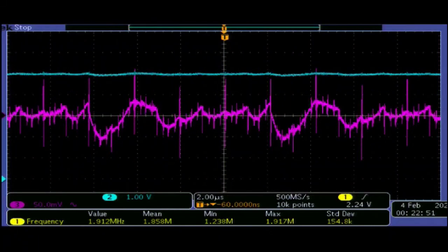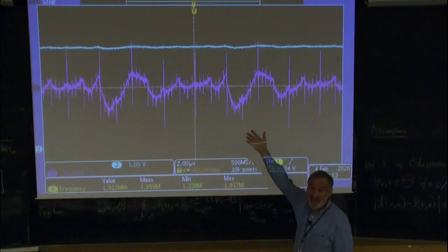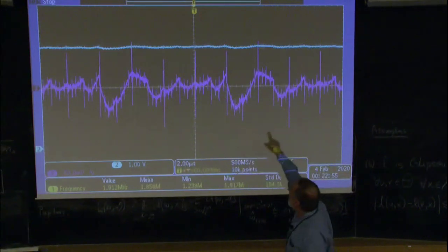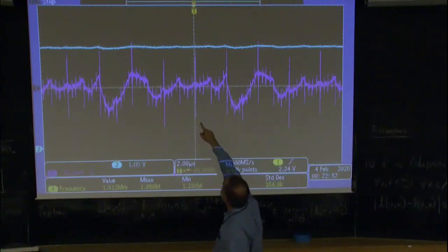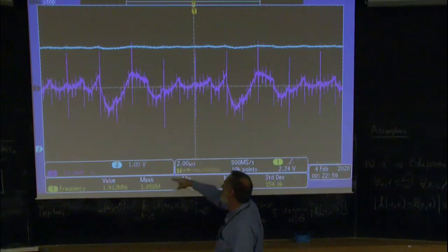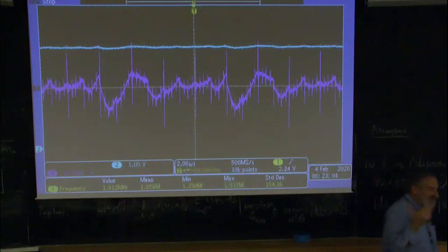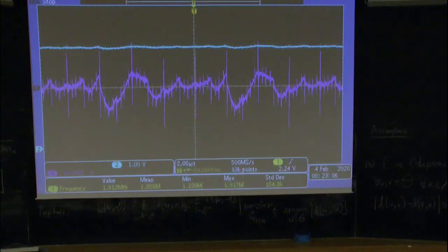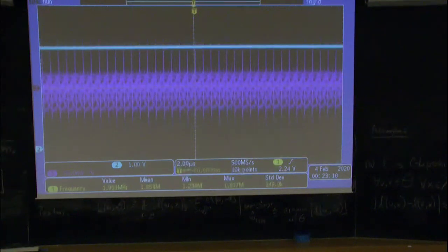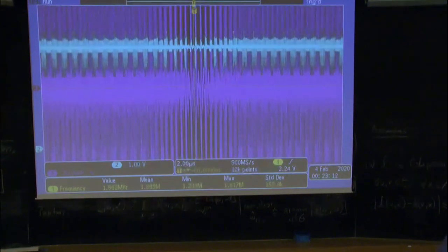So first of all, on the 5-volt line, it now looks pretty good. It's pretty close to being 5 volts. And here, I now have a 1, 2, 3, maybe that's 150 millivolts rather than 1.5 volts. I fixed this circuit by a factor of 10 with 1 bypass cap. So the takeaway here is you should always bypass your circuit.